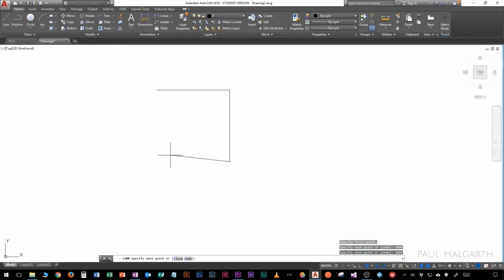Now at this point, instead of having to type in 1000 here, I can actually hover over this line that's already drawn at 1000 and then pull down, making sure that I get this green dotted line and the black X on the cursor. That means that it's now object snap tracked to that point, and when I pull down, when those two snap to straight like this, I can click, and now I know that new line is 1000 millimeters long as well. This really speeds up our workflow. So you're pretty much always going to have the object snap tracking button on.